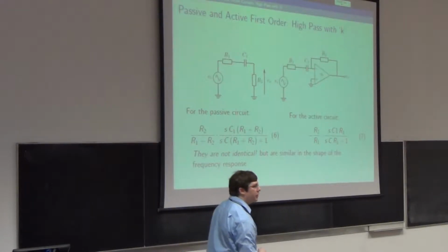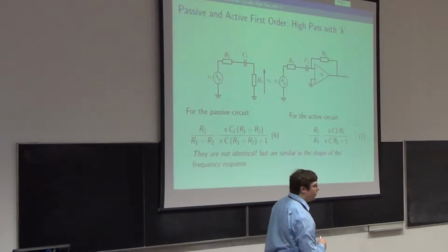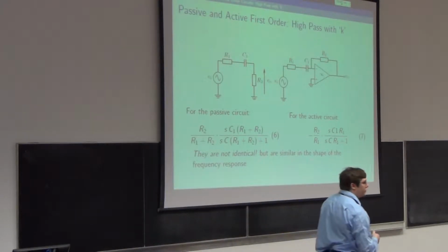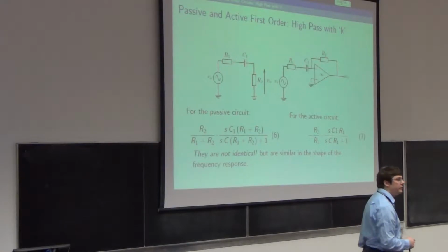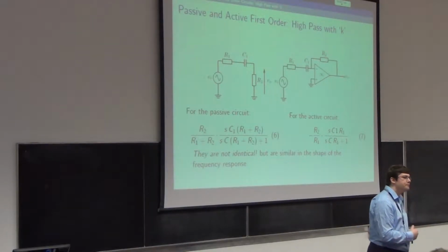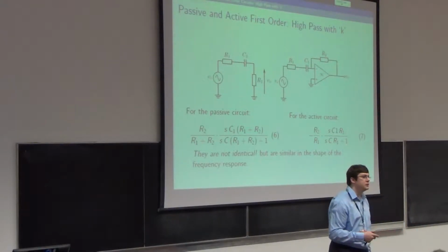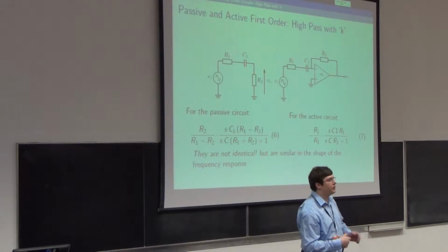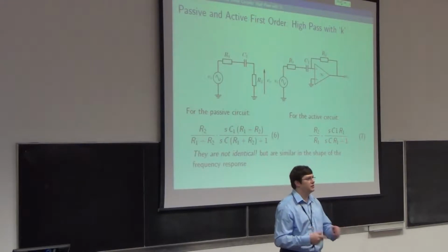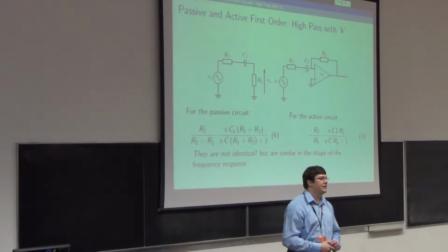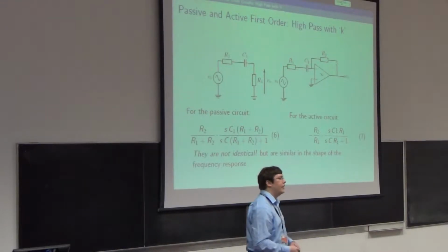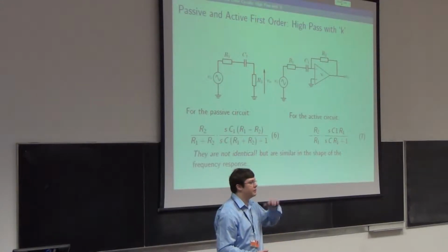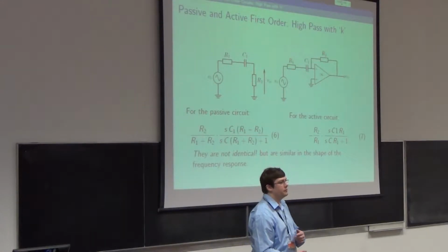If you don't bother with your biasing currents, you'll find that you can't turn on your differential pair properly from the anatomy bit. And if you can't turn on your differential pair properly, feedback won't work properly because the transistor won't be turned on. You won't have an op-amp, you'll have a circuit that dissipates a small amount of heat and doesn't really perform any useful function. Your output will either be locked up at plus whatever your supply is, or locked down at whatever minus your supply is.